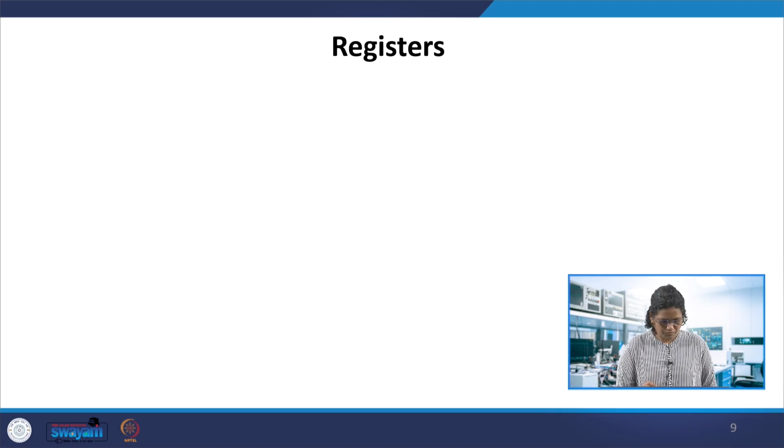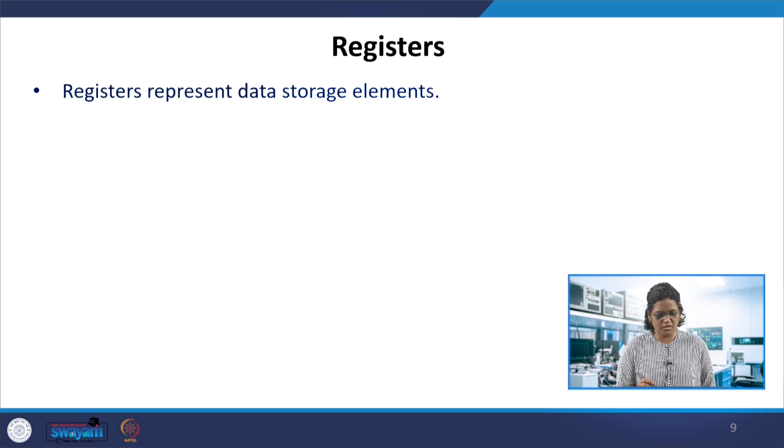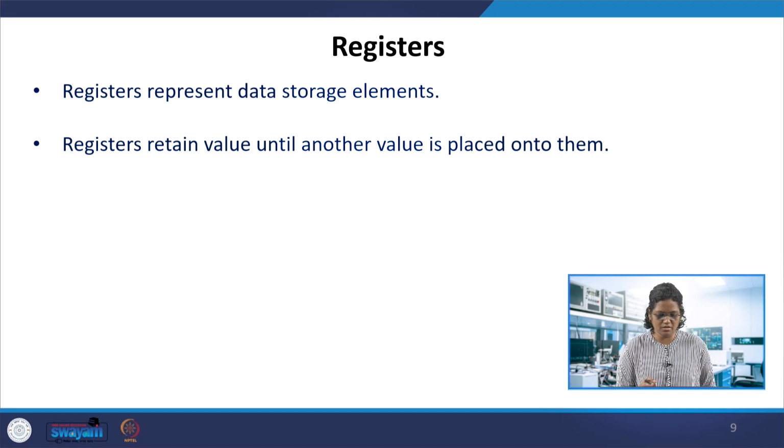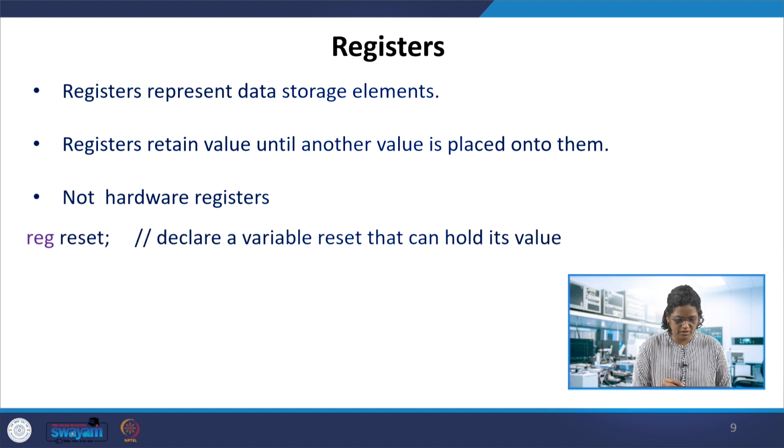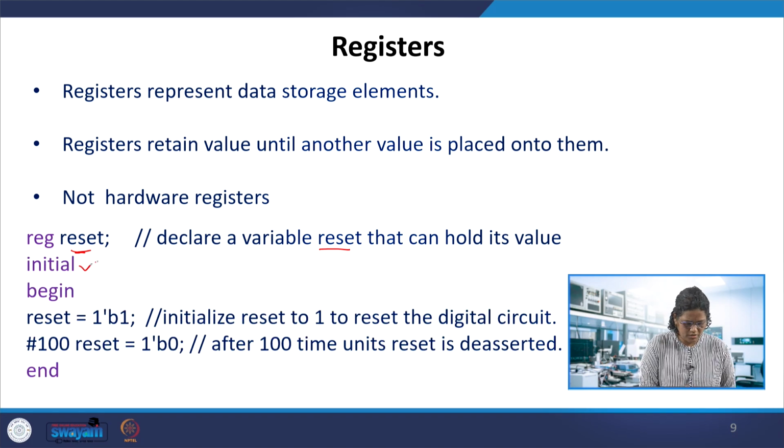And coming to the registers, a register can be a data storage element. It retains the previous value. When you say reg, it is not a physical register, there are no hardware registers in this. So when we declare reg reset, it is going to be a variable reset that can hold some value. And the keyword initial executes only once. So it's a behavioral description.